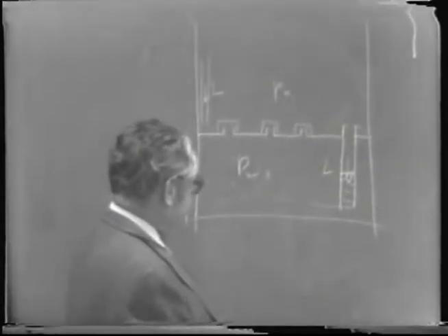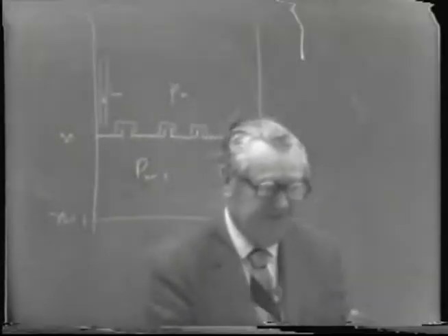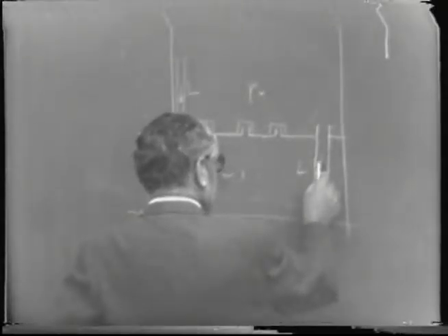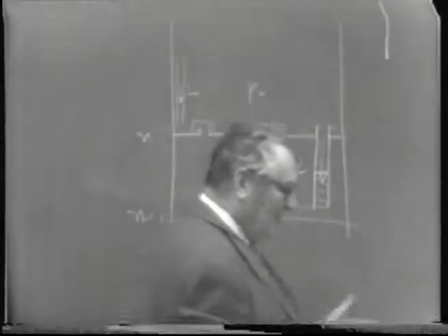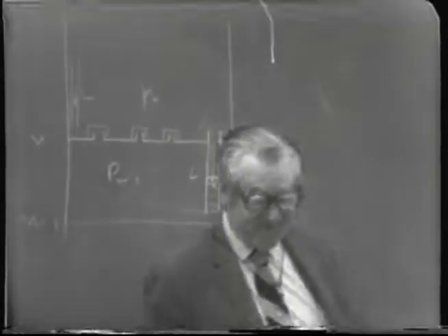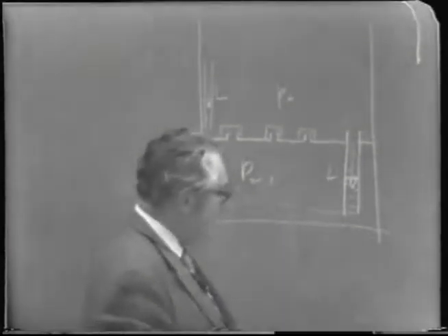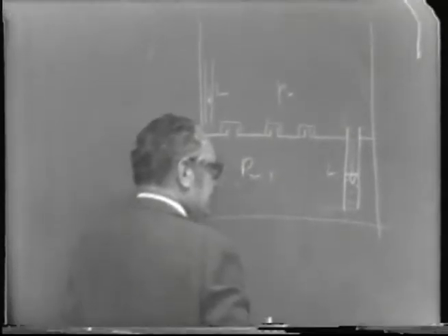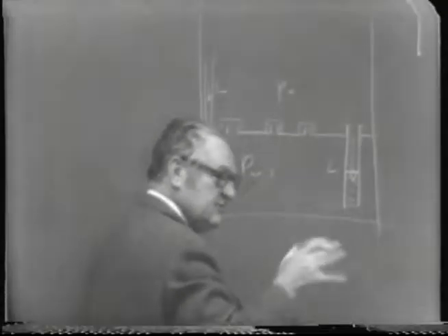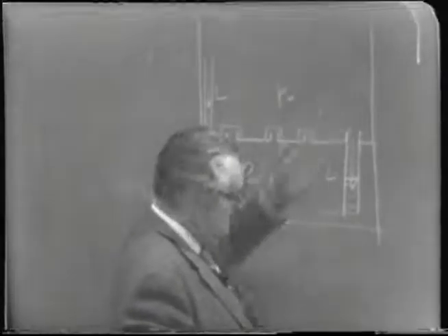And so the consideration here is that because we sometimes have foaming in here, for which the density of foam is sometimes considered to be roughly half of that of the liquid, but of course that depends on the kind of foam it is, but that's kind of a general rule, that the foam would be half the density of the liquid. So if you have any appreciable frothing or foaming, you have to have a little space here for this to break up, and otherwise it'll accumulate up on the tray above.